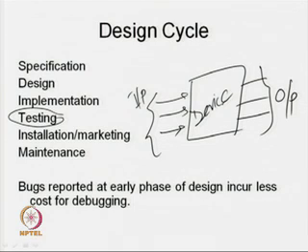No, we know the output behavior of this device according to this particular input combination. What input combinations do we have? During testing we are going to test for those particular input patterns and see whether we are getting the desired output or not. In this case, we are looking for actually two types of testing: one is functional testing, the second one is manufacturing defect, because during fabrication, during manufacturing, some fault may come into the picture due to faulty manufacturing.